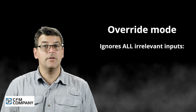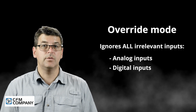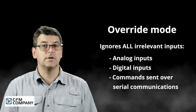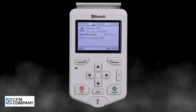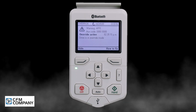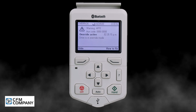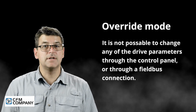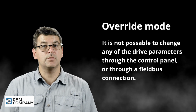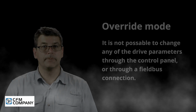When triggered, the drive enters override mode and ignores all other irrelevant inputs, including analog inputs, digital inputs, and commands sent over serial communications. The display of the control panel will show a message that the override is active. The hand, off, and auto keys on the control panel are disabled. When override is active, it is not possible to change any of the VFD's parameters through the control panel or through a field bus connection.